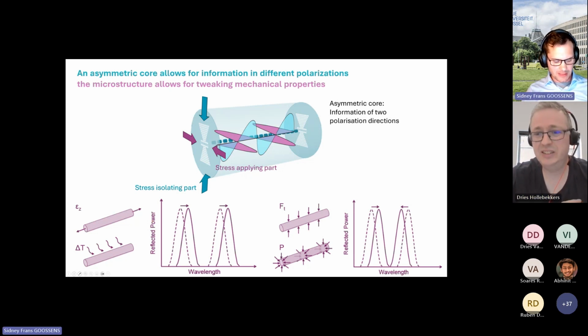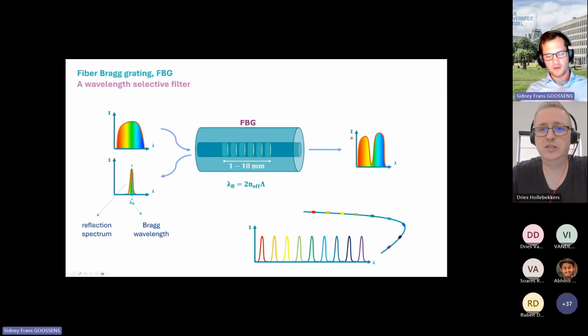Yeah, so that depends typically on the measurement device. So I'll go back to the FBG sensor here. It's a completely physical, analog phenomenon. Phenomenon, difficult word today, apparently. If we apply a temperature here, that temperature will change the physical properties of this grating, meaning that this peak will shift to the left or the right. Now, not to go into too much detail, but in your measurement device you have a system that detects which color is being reflected and how that color changes to the left or the right.